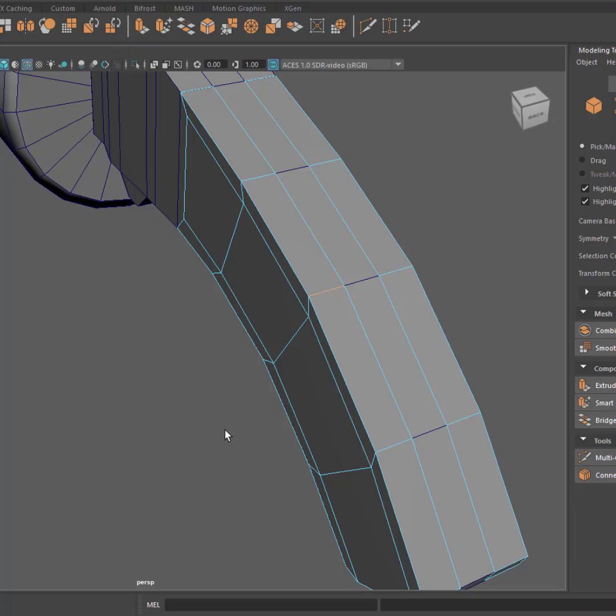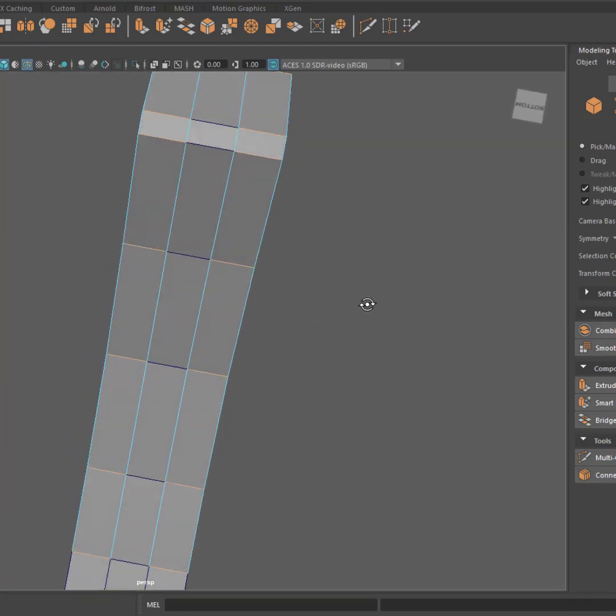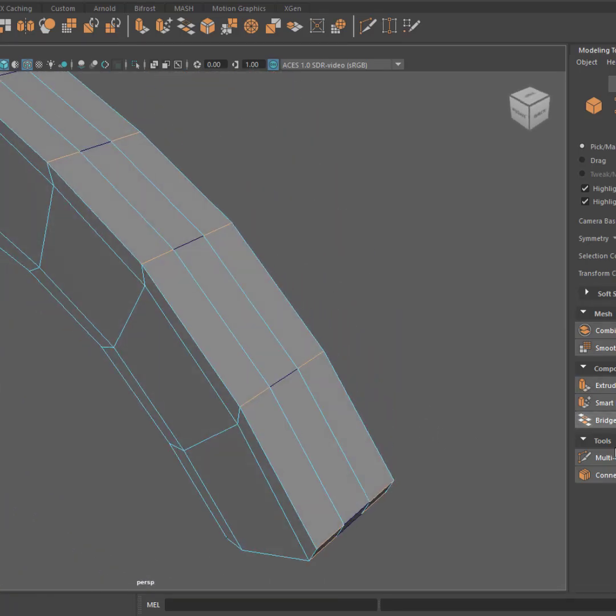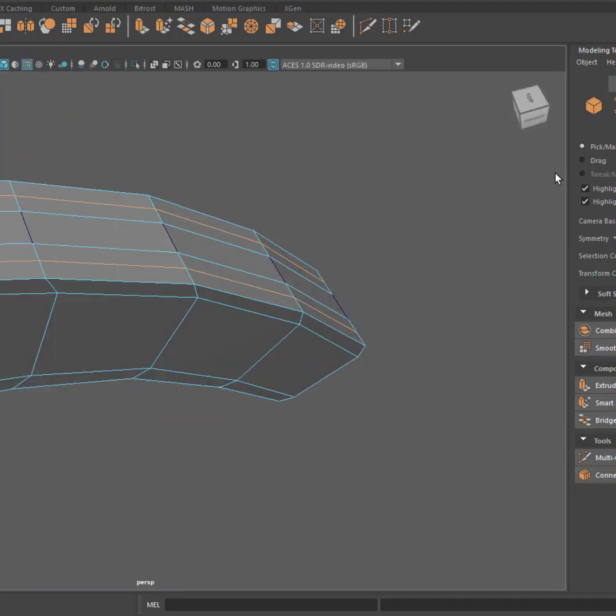Pressing Q, double select this, hold shift, double click the next, I have selected the ring. Again, this, double click the next. So I've selected the ring connection, and then I'll just choose connect. I'll choose one only, and then switch to the Q or selection tool. This time I switch to the vertices.